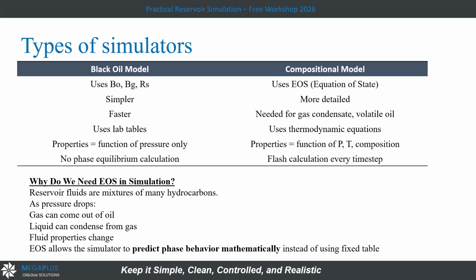The model depends on the schedules that I inserted from the CCE and the DLE, differential liberation expansion, experiments. So the model will have its pressure decline, and from the new pressure it will get from this schedule the capillary pressure and relative permeability that we discussed yesterday, the formation volume factor, the viscosity and all of that. So it's normal inputs.